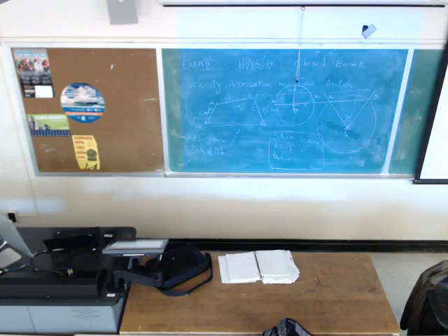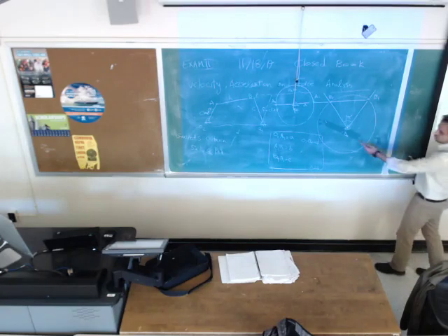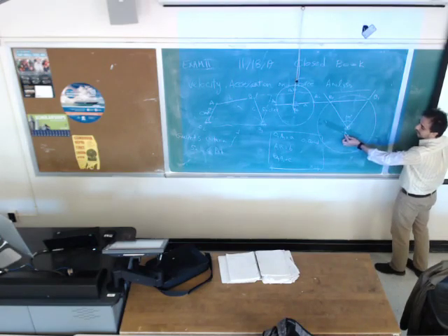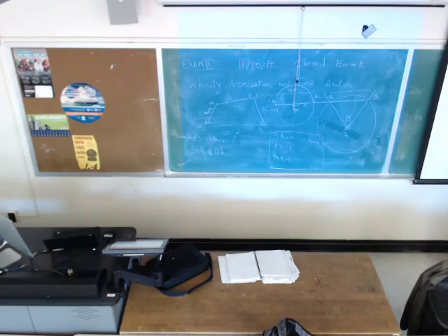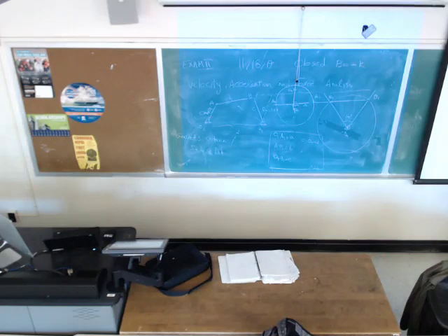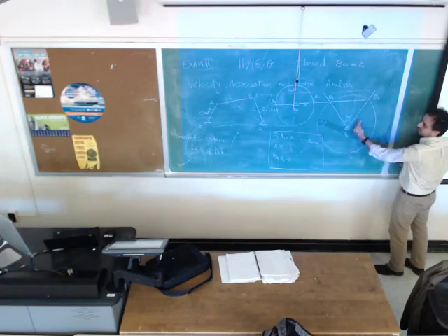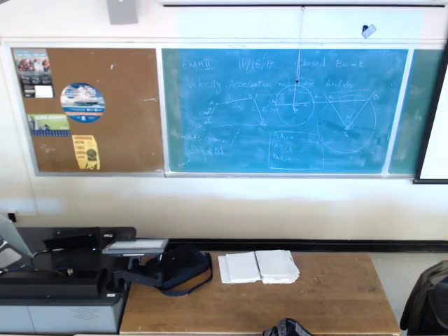Here you see, I said for this problem we are going to have 5 free choices. How do I count 5? We are working in 2 dimensions, x and y. So I pick the x and y location of O4 as a free choice. You can pick any x and y for O4, so you already use 2 free choices here. You can draw this line at any angle with the ground line. So number 3 is the angle of the line with the ground. It can be at any direction. So 3 free choices are already used.